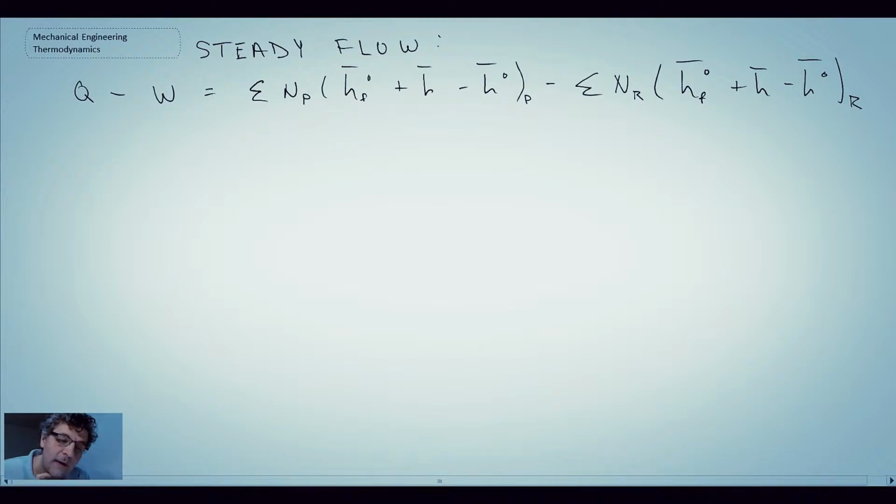Now we're talking adiabatic flame temperature. Adiabatic means there's no heat transfer, so that's gone. And steady flow typically does not have any kind of work involved. Consequently, the first law can be recast into just a balance of the enthalpy of the products and the reactants.